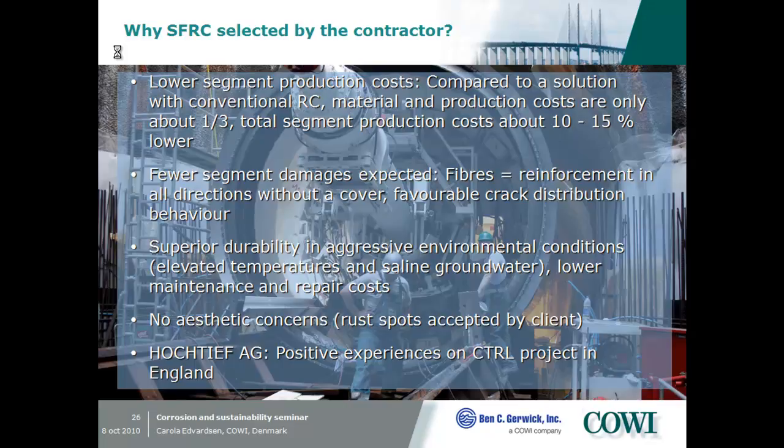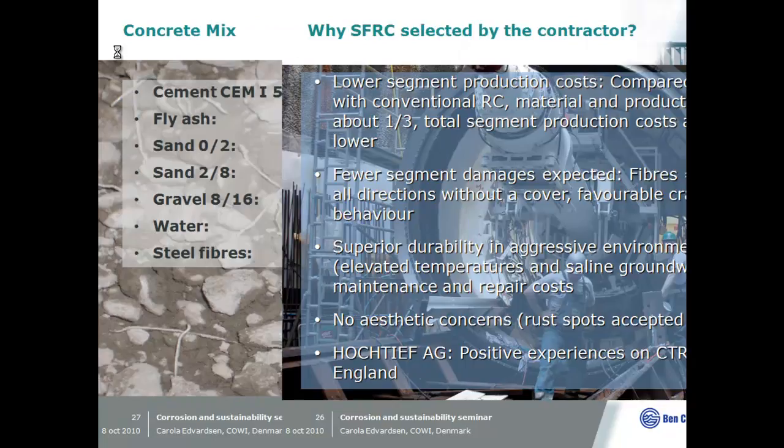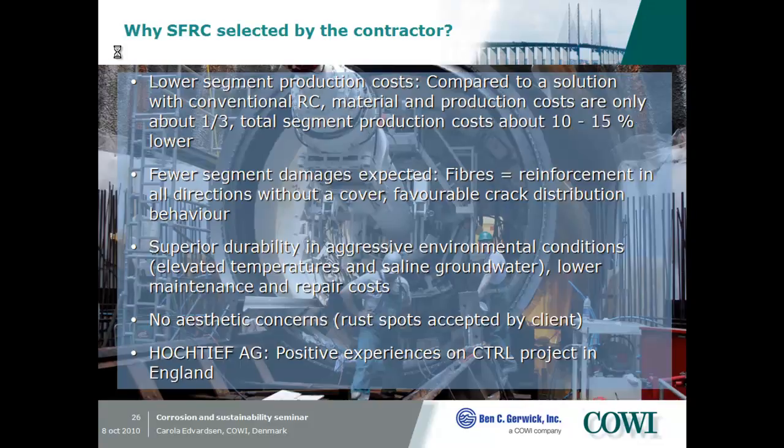Because normally we have some damages if a tunnel bore machine erects the segments inside the tunnel. And it has a superior durability compared to traditional concrete. Please be aware, in a bore tunnel we normally need reinforcement only for the transport and for the handling. Afterwards, we do not need reinforcement because a bore tunnel is under compression during normal operation. Why put in traditional reinforcement, which can only corrode in some years, when it is not necessary?